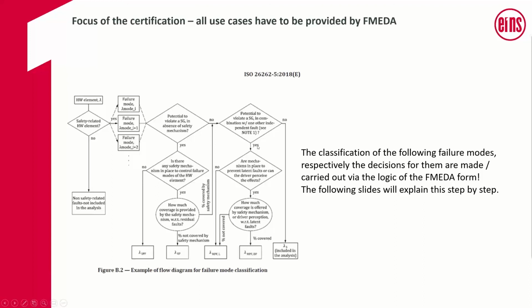Are you a multiple point fault? If yes, then you can also determine: is it covered by a safety mechanism with a diagnostic coverage? Then you have the multiple point fault, the latent multiple point fault failure rate and the detected one. And also here, if the single point fault is covered with a safety mechanism, then you will go to the residual fault, and this one, which is covered by the safety mechanism, goes to the FIT safe.